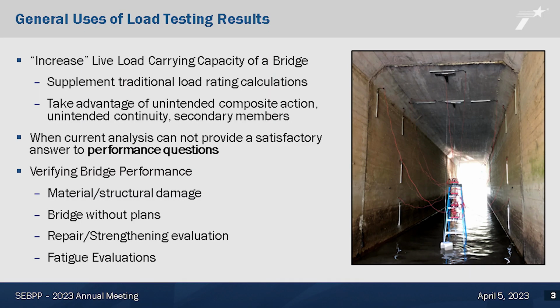Other ways that load testing can be used is to verify bridge performance, maybe after a strengthening project is complete, to verify that a structure is performing as it was intended, especially when we have new technology. So yesterday there was a mention of titanium strengthening. Early on in the implementation of titanium strengthening, instrumentation was used to verify, hey, we're getting proper performance out of that new technology.